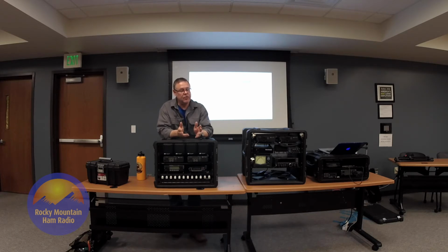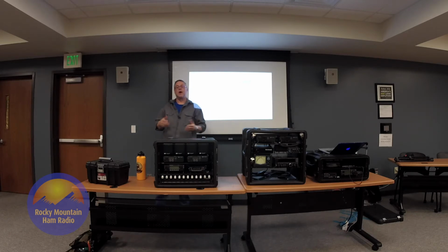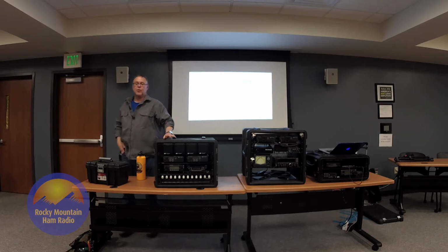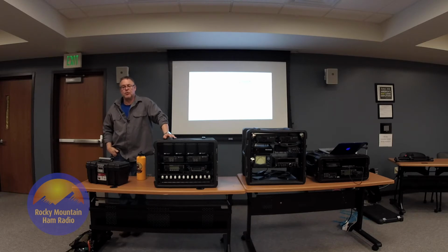If you're looking for a serious radio operation-based generator, and also one to use for backup for your house, make sure it's a modified or pure sine wave generator, and that it's an inverter type generator.